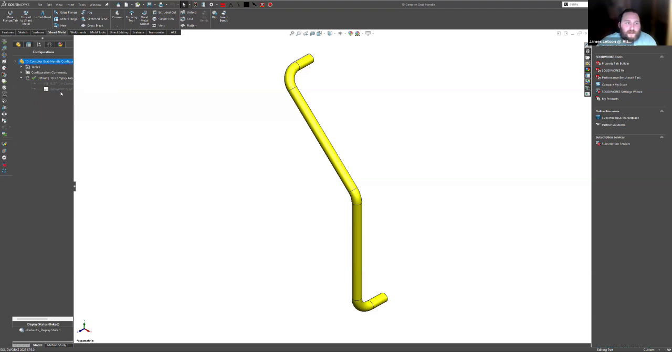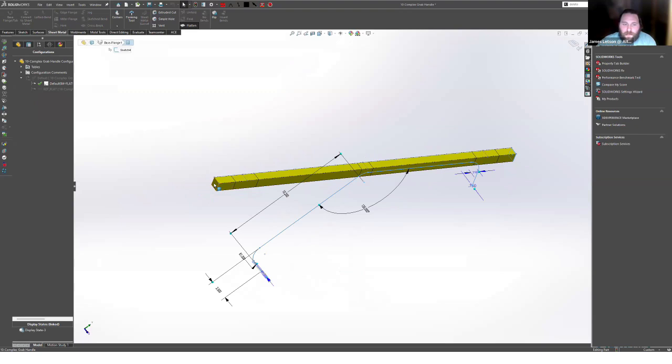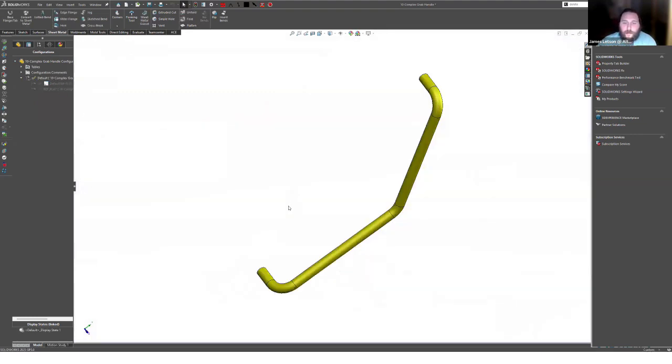So the same thing, when I make this active, you can see that it is now square, and we can measure an actual length. We know that this particular grab handle needs to be 26.643 inches long to be able to get the final formed length that we want here.